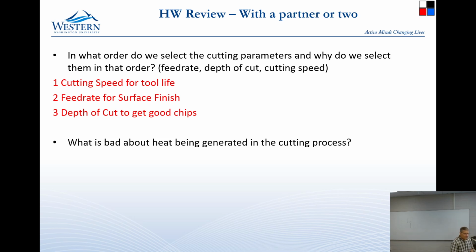If the tool is hot, will it wear faster? Yeah, so the hardness of everything drops off quite a bit as it gets hot. And so if we heat up the tool, the hardness of the tool goes down. And as the hardness of the tool goes down, then we will wear the front face of the tool, and then it won't be the shape we wanted.